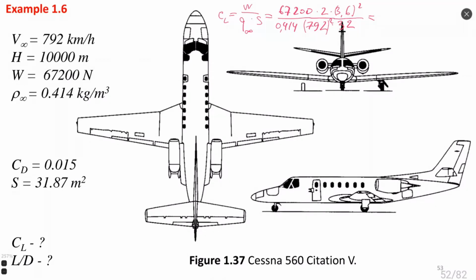Yeah, probably. I received 0.21. This is a good value for lift coefficient. I mean good because it's not so small, not negative. It cannot be negative, right? But it can be very, very small, which usually is not possible for sustained flight. It must be something realistic and cannot be too high. About exactly how big or small the values could be, we will speak very soon.